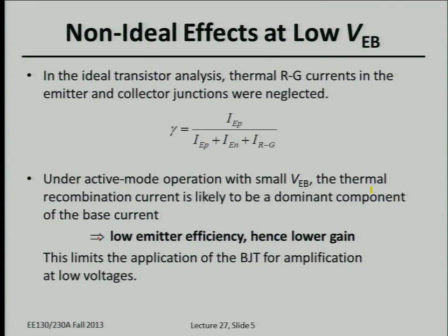Other non-ideal effects, there's two classes. Similarly to a PN junction diode, non-idealities show up at very low current levels and also at very high current levels. Okay, so it's very similar to a PN junction. This generation recombination current component is usually small, and so we don't care about it unless you're operating a PN junction at very low voltage and therefore a very low current level.